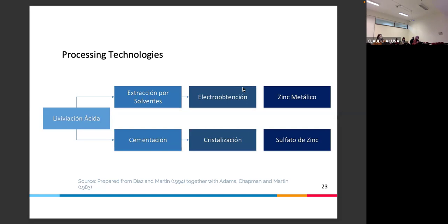So 1 means you have a paper, you have calculations, for process engineering. 2 means you have a bench scale, very small one, let's say a leaching process in a 100 centimeter solution with 2% solid. 2% solid is very dilute, it's not for commercial purpose, but it lets you know what the conditions are, pH, oxidant level.